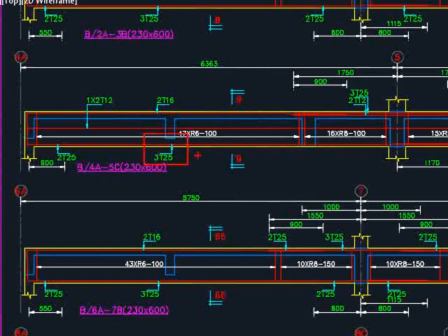Indicate the amount of reinforcement bar required. Do some curtailment. Indicate the locations where you can reduce the amount of reinforcement bar near to the support. You see here there is an offset distance between the grid line and the starting of the beam.